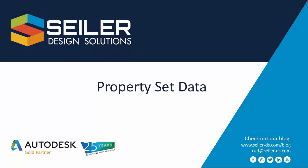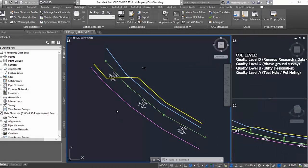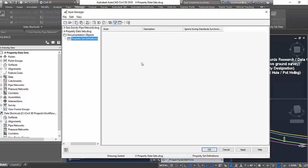In this video, Property Set Data. New in Civil 3D 2018 is the ability to define and use property set data to add extra attribute information to your Civil 3D objects or drawing objects within your Civil 3D drawing. To define property set data, in the Manage tab of the ribbon, click the Define Property Sets button.